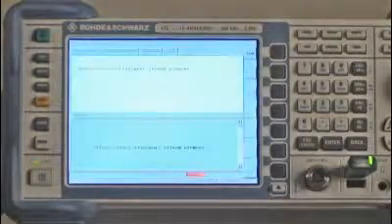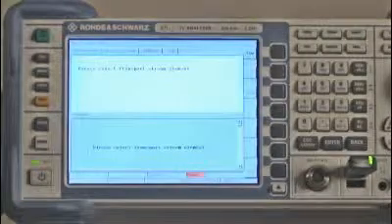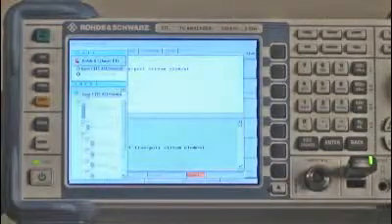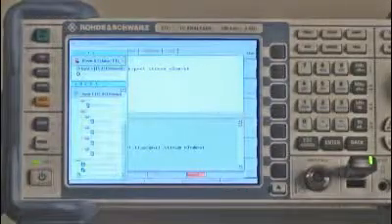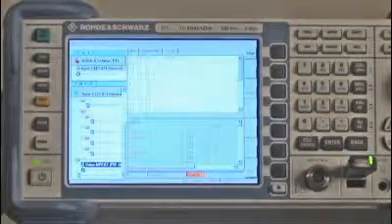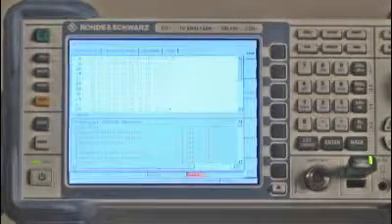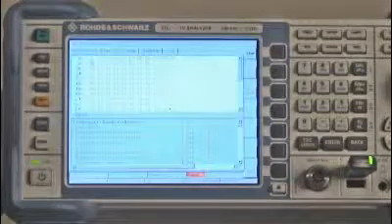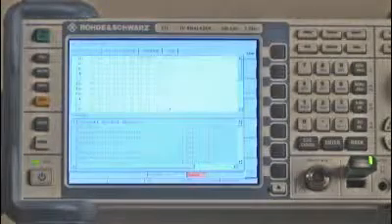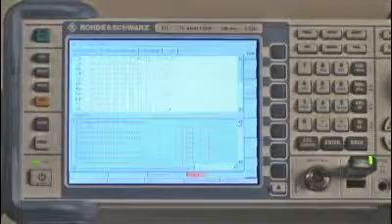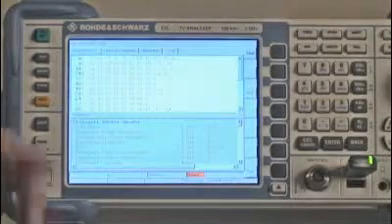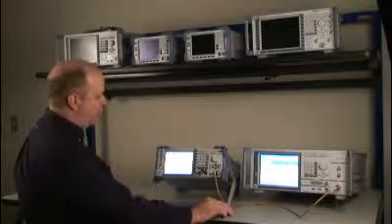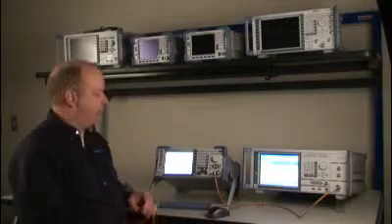The interpreter is exactly that. It will interpret whatever table I select on the left-hand side. For instance, if I wanted to look at the values of the video packet, I can always see my header information at the top with the hex 47, which is the sync byte, going all through the hex values within the video. I can either have a snapshot or I can have this run continuous. And this would be good for more in-depth analysis.